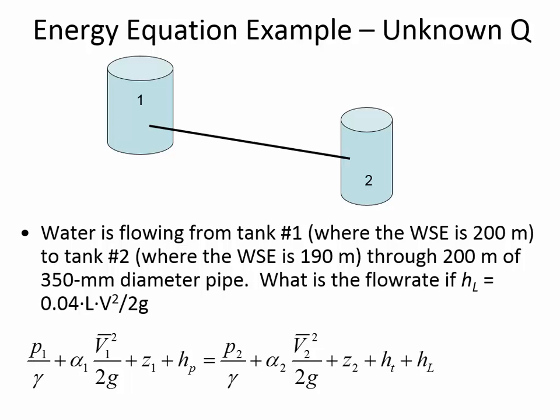Now, this situation is going to change over time because as the liquid level decreases, as the head falls, the driving force is going to be decreasing. And so that flow rate is going to be going down, and it'll slow down as the 2 elevations get closer together. So it's a declining rate in the same way that for an orifice equation, as the